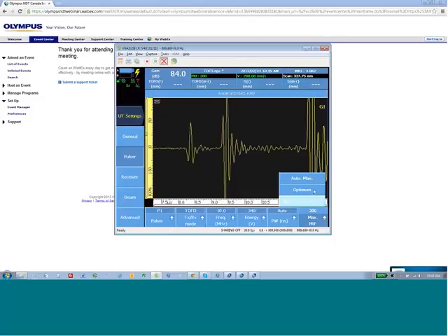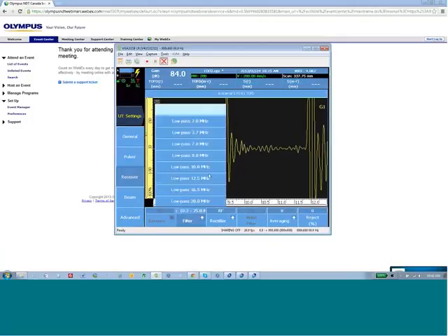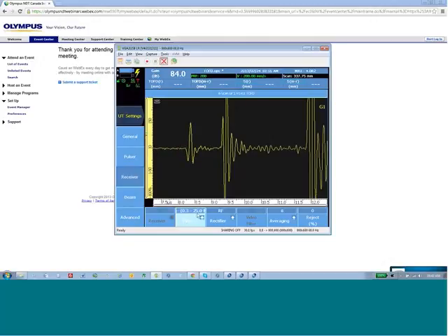Probably 1/2 of the culpability for the OmniScan's reputation for weak TOFD was due to PRF management generating excessive noise when combined with use of averaging. That has been corrected, and we see an enormous improvement now in both signal-to-noise ratio and detectability in B-scan imaging as a result of software in addition to hardware. So we select the receiver, select the filter of the frequency or whichever filter produces the best results, including no filter if the results are better.